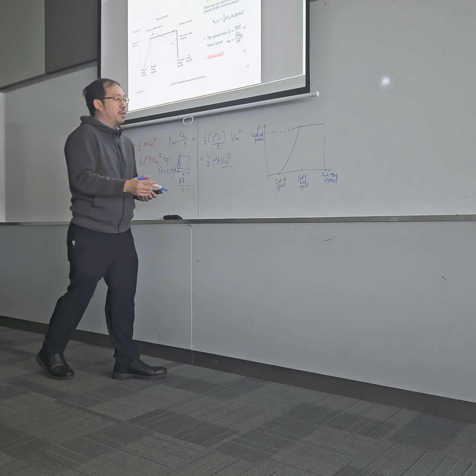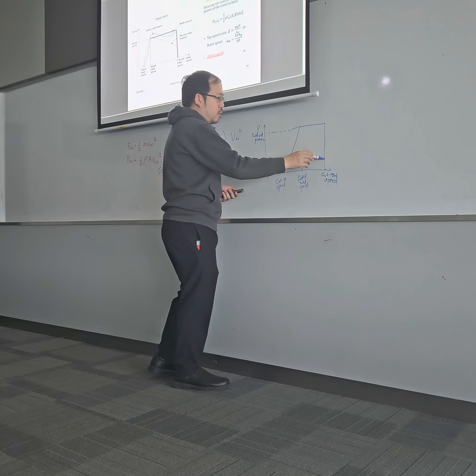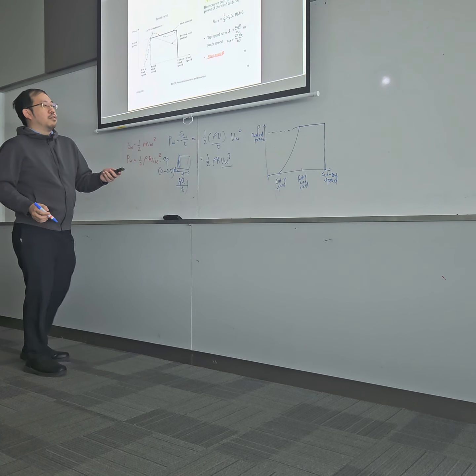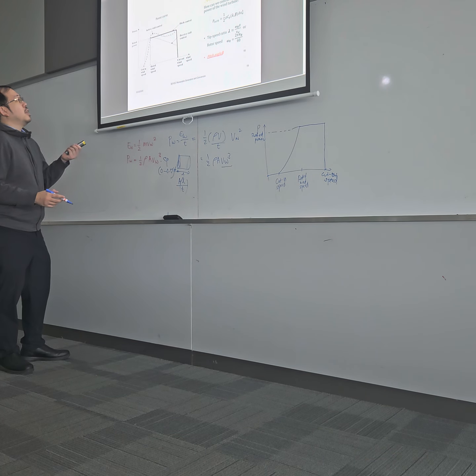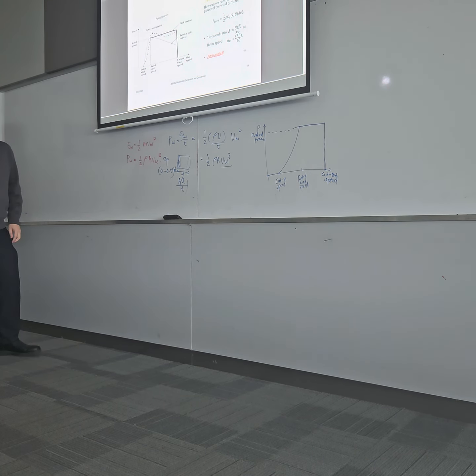So you have a couple of ways to manage this at the values that we have set here. One is the active stall control. So there is a way for us to stall the wind turbine. You may want to stall it after the rated wind speed. It may be slower than the pitch control, but at least you will get it to come down towards the rated power. So actively means you will have to do a control and then they will adjust accordingly.